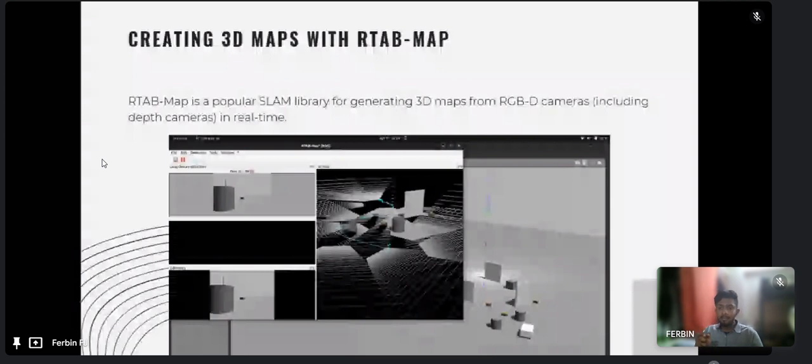Using that reference with the help of IMUs and encoders, we were able to come up with an idea with which we can autonomously run a path planning algorithm like A star to clean the hull. For that task, the depth camera was very useful, and it was one such good example of how depth cameras are generally used in robotics.